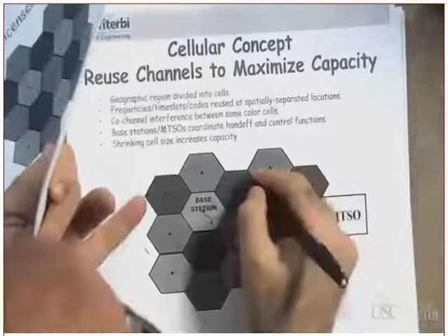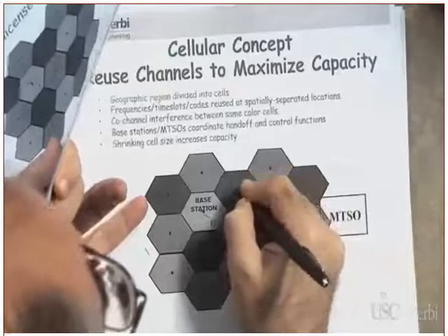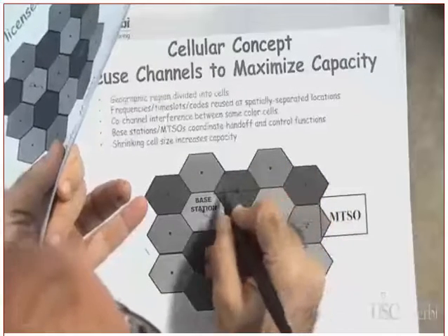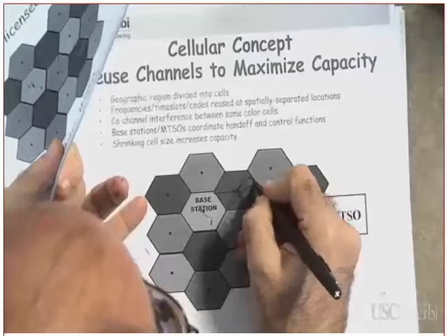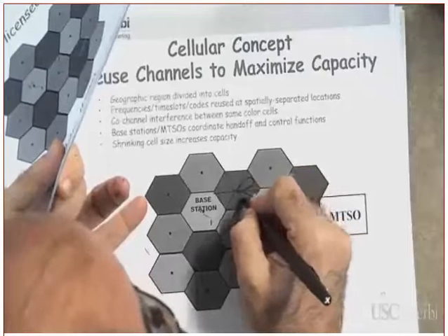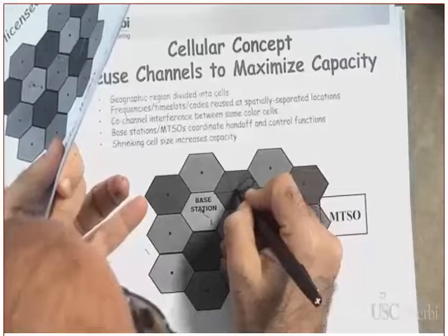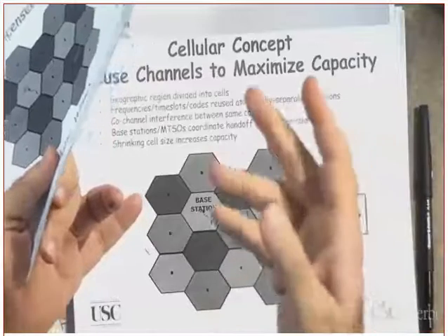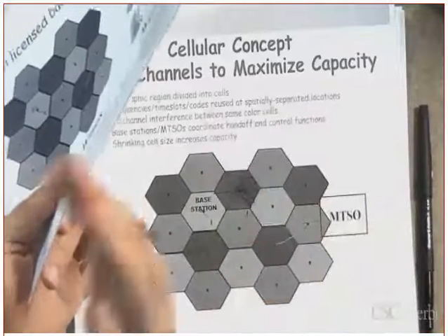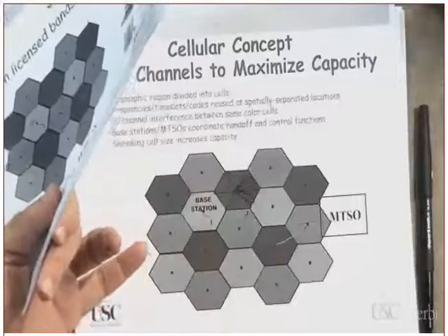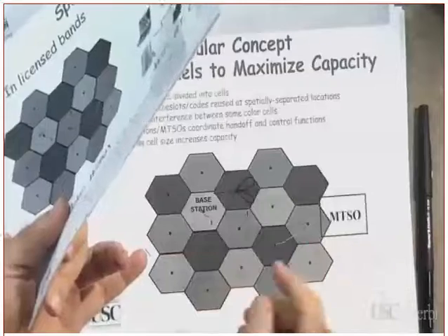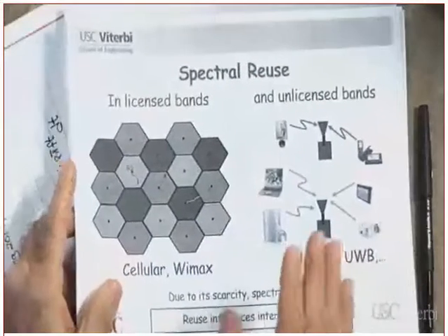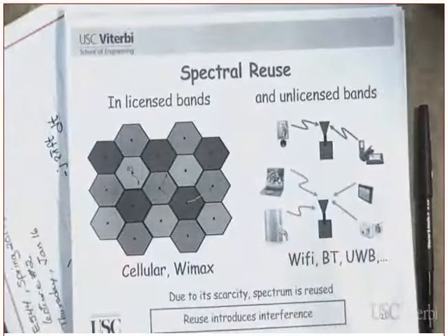The antennas become like this. This is the directional antenna here. I divide it into how many sectors here, for example, 1, 2, 3, 4, 5, 6. The antennas will become directional. Notice, by the way, the antenna will also have some side lobes and back lobes, but their effect will be negligible, especially the back lobes. Clear? You can reuse the frequencies to increase the capacity. But when you design your system at the beginning, you need to design it based on coverage. You need to attract people first.